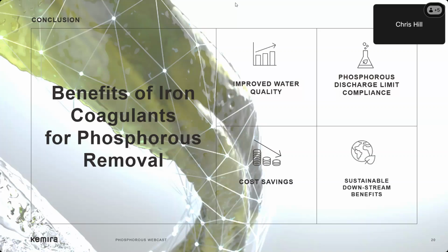Some additional benefits of using ferric salts are that they remove hydrogen sulfide, enhance cake dryness, and treat struvite in the entire process. Optimized coagulant usage results in less chemical sludge and therefore lower biosolid disposal costs and reduced polymer usage costs. This is due to the downstream benefit of higher sludge dissolved solids obtained through the addition of iron coagulants.